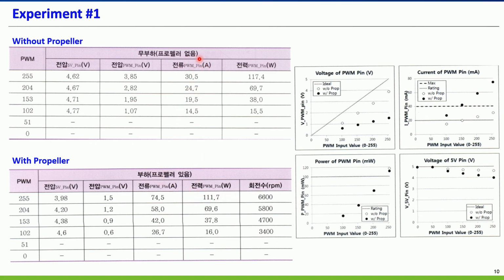I think this one is not ampere, this one is a mistake. I think this one is milliampere, should be aware. Milliampere. I think this one is also milliampere. Maybe somebody typed it wrong. 74.5 ampere is very big; you can damage the motor. Anyway,